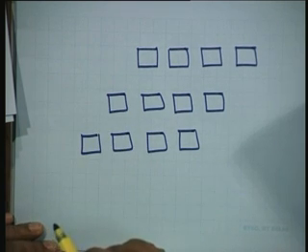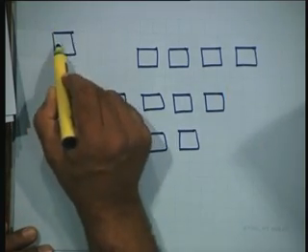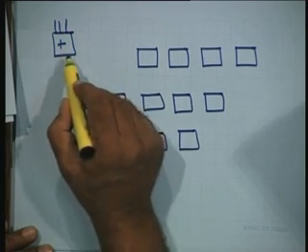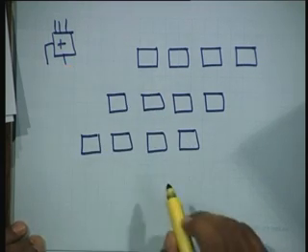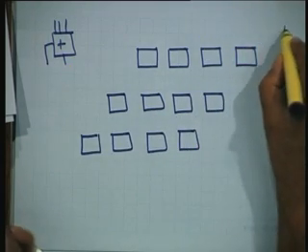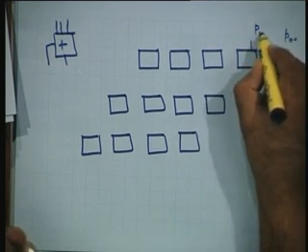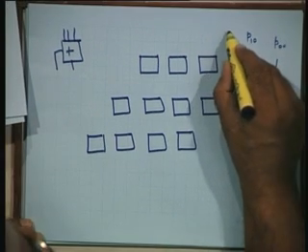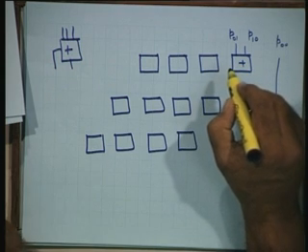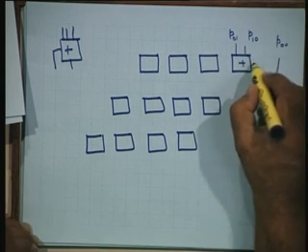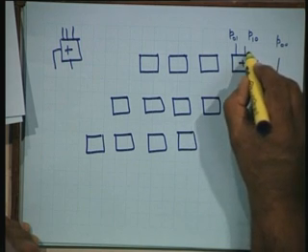So, we will require the same 12 adder units, and each of these I will look at in this form. It takes 3 inputs, you can put them in any order, and generates a sum and a carry. So, P 0 0 I let go straight. P 1 0 and P 0 1 are fed here. I have nothing else to feed here. I could have fed one more here, but there is nothing else to be fed. So, maybe I can leave 1 0 here.